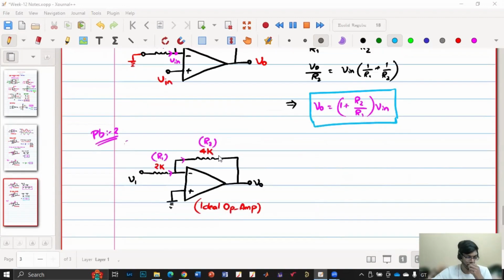So in the majority of applications, except the Schmitt trigger, the op-amp is always used with negative feedback, because we want the op-amp to operate like an amplifier. Negative feedback has wide application, and positive feedback has few applications, very focused on particular uses.